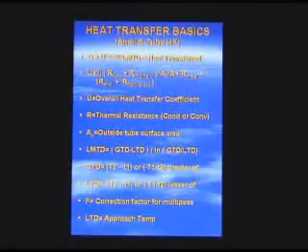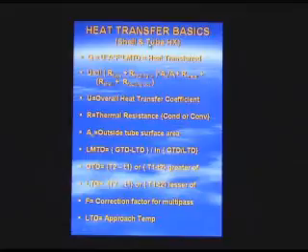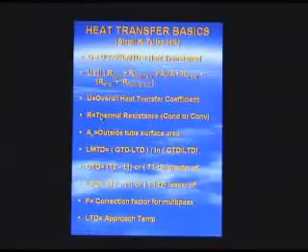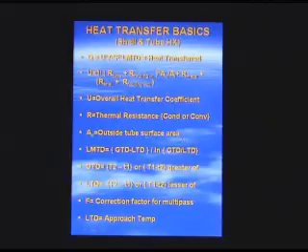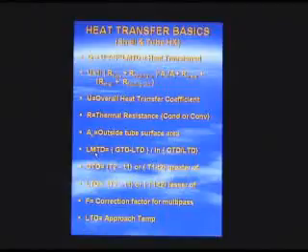Okay, continuing, we were talking about the basic Fourier heat transfer equation. I think we were talking about U, the overall heat transfer coefficient; R, the individual thermal resistances, tube side and shell side; A0, the outside surface area of the tube to which everything has been corrected; and LMTD, the log mean temperature difference.